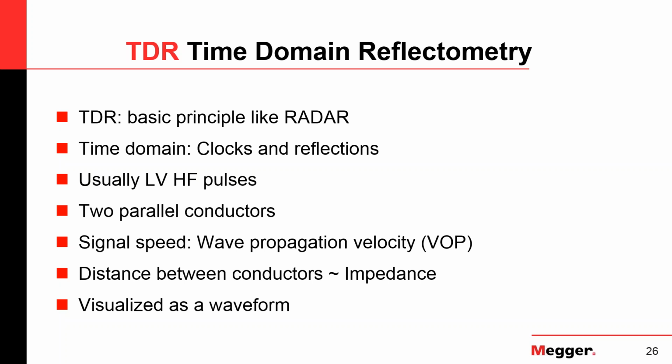If these conductors are too far away, your 20, 30 volts get diminished, so you don't see much. That's one problem. So you need a fairly close return conductor to make that work. And so the pulse travels in between, and it travels at the wave propagation or velocity of propagation.